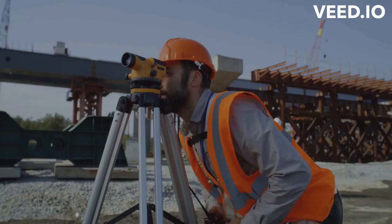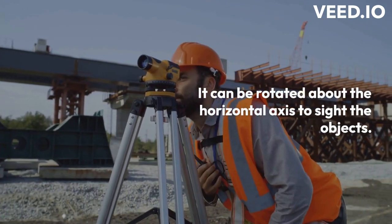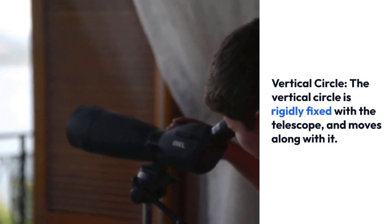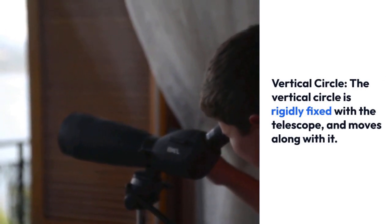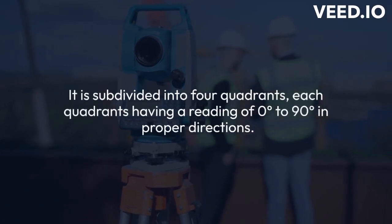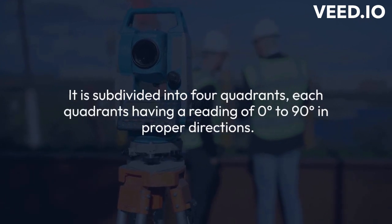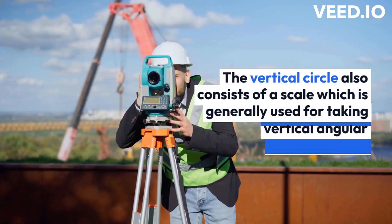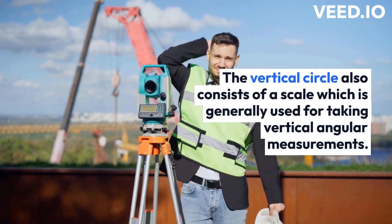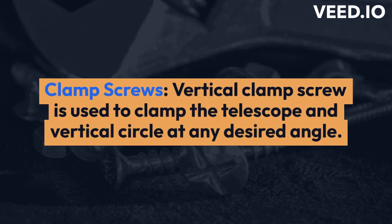Vertical circle. The vertical circle is rigidly fixed with the telescope and moves along with it. It is subdivided into 4 quadrants, each quadrant having a reading of 0 deg to 90 deg in proper directions. The vertical circle also consists of a scale which is generally used for taking vertical angular measurements. Clamp screws. The vertical clamp screw is used to clamp the telescope and vertical circle at any desired angle. It prevents the rotation of the telescope about the horizontal axis.